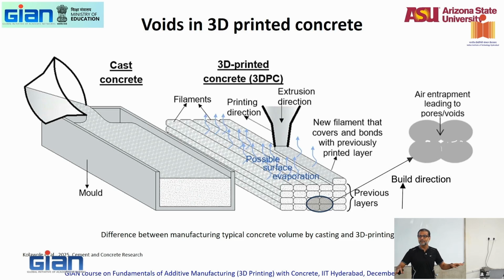You account for all of that and you eventually end up with a 40 megapascal concrete and you say, okay, I want 30, I will need 40. You ask the ready mix supplier for 40, he will give you 45 or 50. Right? You end up always with a higher strength and higher properties. So, and here is my point.